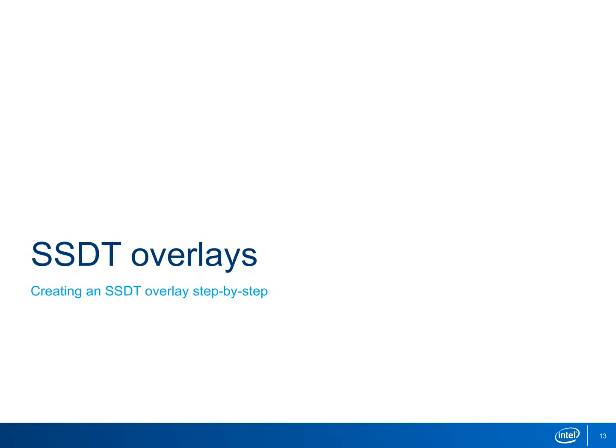The SSDT overlays are produced from small excerpts of the ASL code that can be added into the system by the user at boot time or runtime. This is mostly useful during the prototyping phase of a platform in order to quickly change the configuration without rebuilding a firmware.